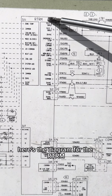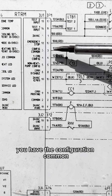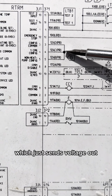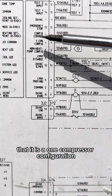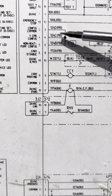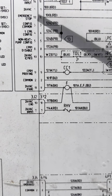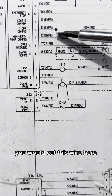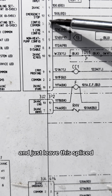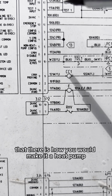Here's the diagram for the RTRM, and if you look right here, this says configuration. You have the configuration common, which just sends voltage out. If it gets voltage in on 4, it's telling the RTRM that it is a 1 compressor configuration. And if that power comes in on 5, it is a non-heat pump configuration. So if you had an RTRM and it was a heat pump, you would cut this wire here and just leave this spliced. This wire would hang and get a wire nut. That there is how you would make it a heat pump.